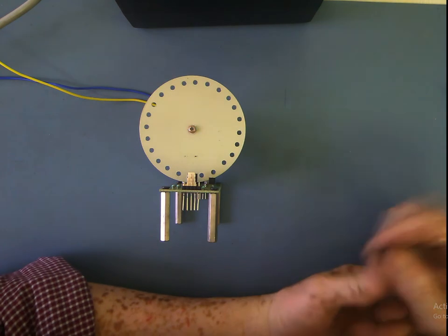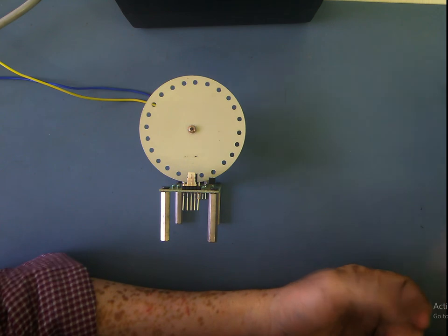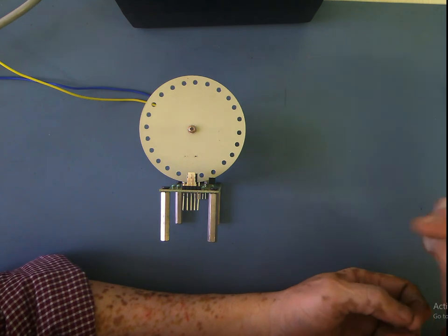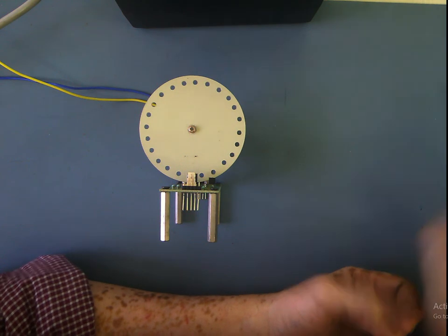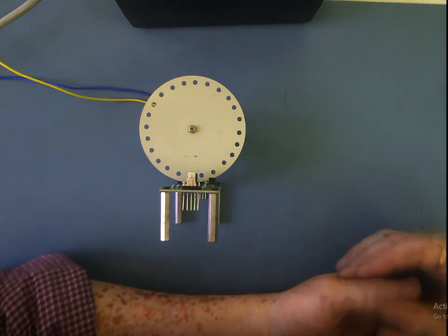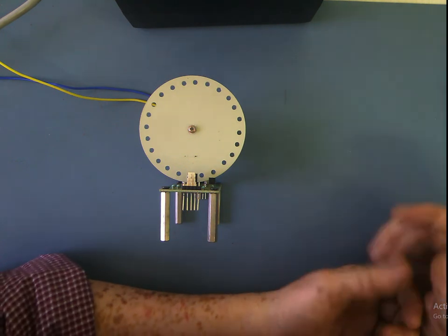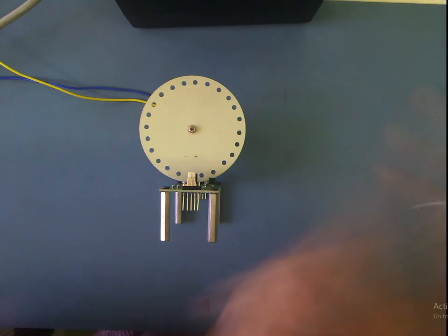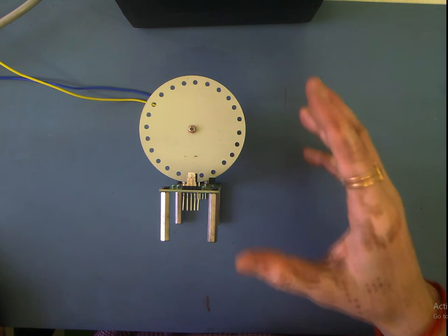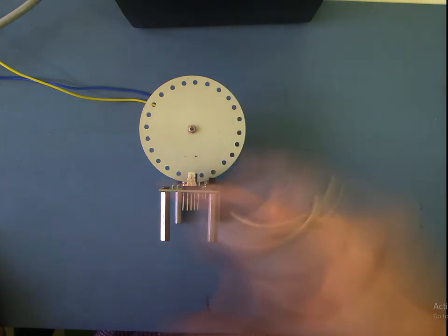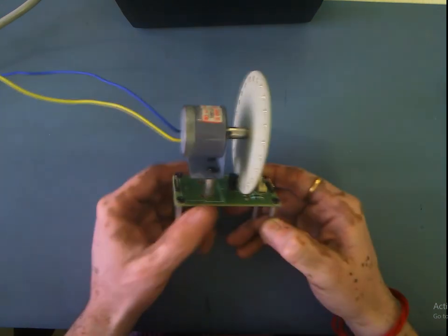Now you see that we can simply use a frequency to voltage converter circuit to convert this frequency to voltage, and then we can calibrate that voltage using other electronic circuits, maybe some op-amp based circuit, to display the RPM. That is a completely separate part of this entire instrumentation. Here we are only detecting the RPM.